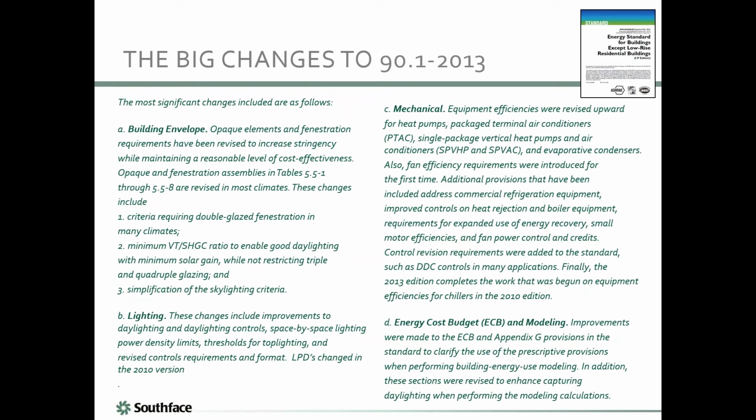It's kind of interesting because in Georgia, you can either use 90.1 or you can use the 2015 IECC. And if you pick the IECC route, it's got its own set of tables. But Georgia decided to delete the ones in the 2015 IECC, and everybody uses the same set of tables. If you think about it, it kind of makes sense because you hate for a piece of equipment to pass under one code and fail under another code. Think about the nightmare that could create. So we're just going to use the ASHRAE equipment efficiency tables.